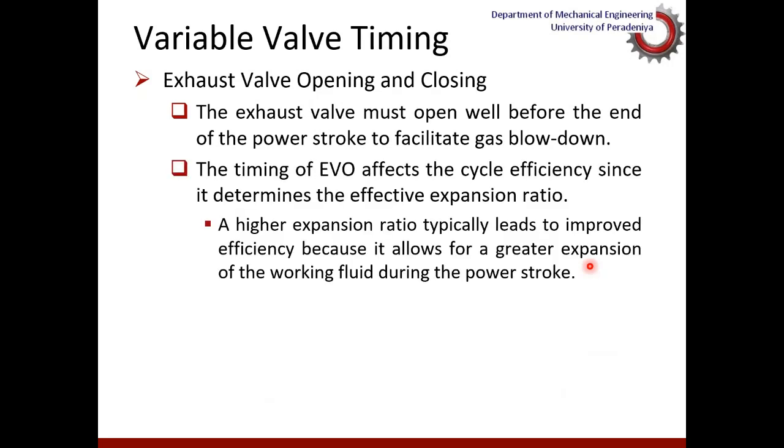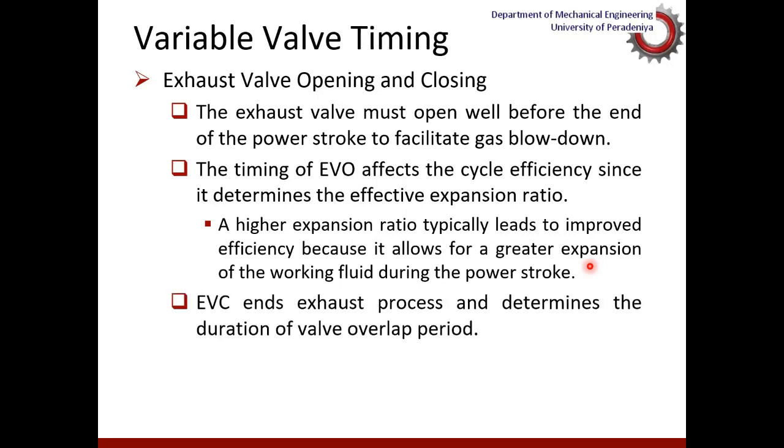At the same time, opening the exhaust valve early would reduce the expansion ratio. That is, you open the valve while the gases are expanding, so the real power that could have been extracted from the engine is reduced. Accordingly, there can be negative effects.